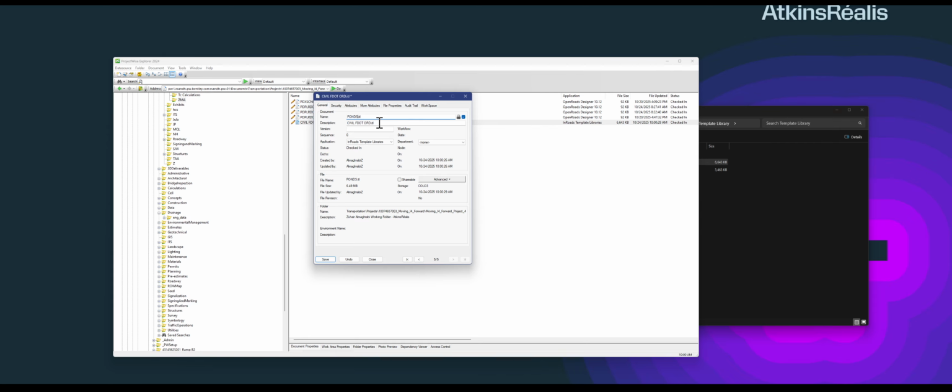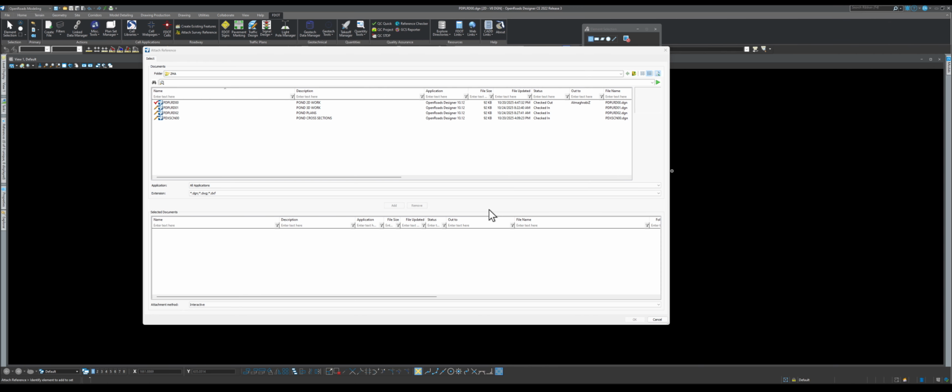So I'm going to make this, like I said, a 2D file. And usually the engineer, who's the one, they actually make the design of those contours. As you know, the pond itself, just think of it as like there are contours, and those contours are like the bones, the structures of how the pond will grade from the bottom to the top. At the top is the berm, where the maintenance cars will drive on it, and then it will go down. So they are like steps. Think of it as like stairs. Those steps need to have an elevation, and also the space between them needs to be designed. Who does that? The drainage engineer.